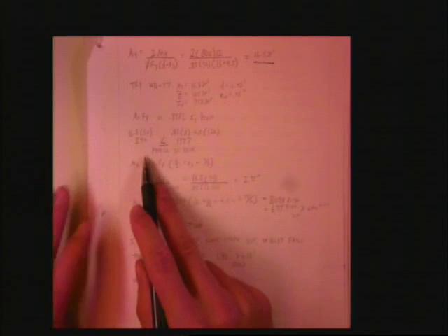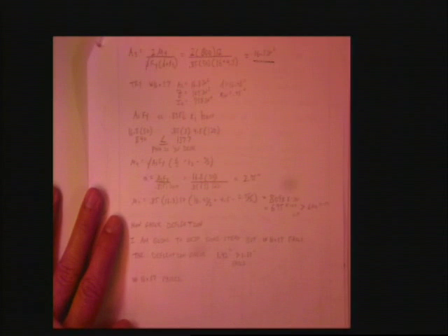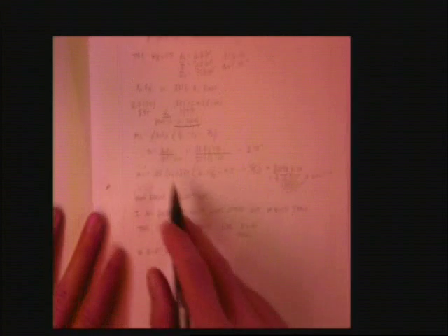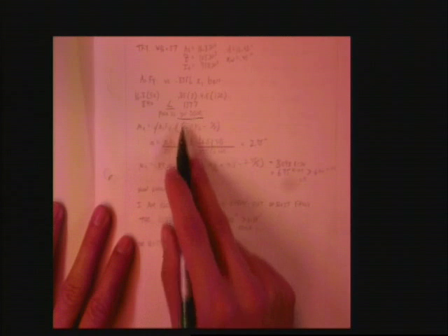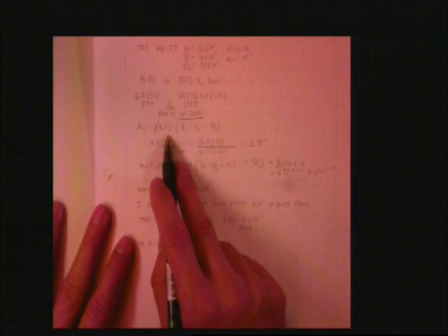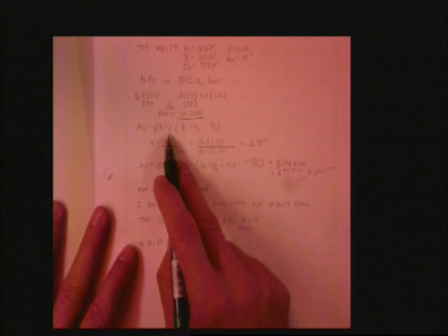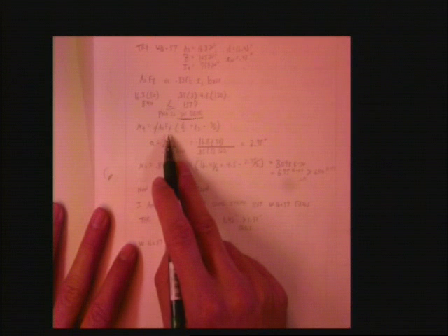Okay, so I'm going to do my same thing. Compare my AsFy versus my 0.85 f'c t sub s effective. Again, I find my plastic neutral axis is in the deck. Guess what? When it comes to your homework, it won't be. Okay? And it's not that hard, but instead of using this canned equation, all you'll have to do is draw the cross-section, find out where that point of equal area is, plastify everything above, plastify everything below, find the resultants, sum the moments about the neutral axis. That's what you're going to do on your homework that's due on Tuesday. Okay?